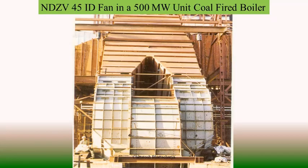And the bearings also, particularly for the fans which are handling high temperature flue gases or high temperature gases, in that case, these are cantilever supported, not cantilever, it is simply supported. So for this simply supported arrangement, there is one bearing towards the motor and another away from the motor. The bearing which is towards the motor, its shaft is connected by a coupling to the motor coupling, or there may be a hydraulic coupling, whatever may be.